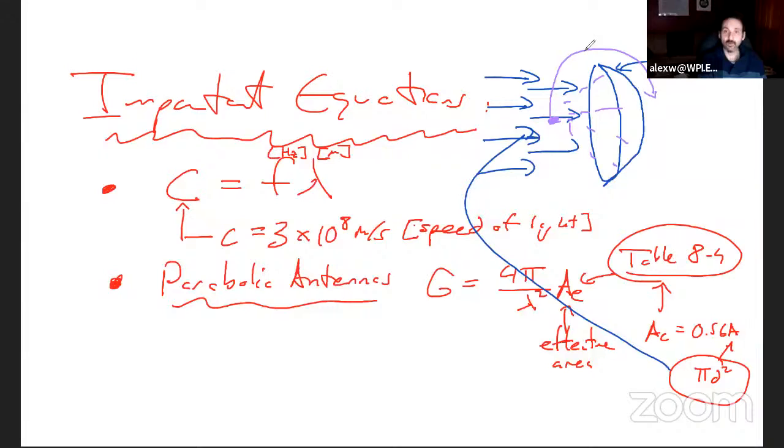The effective area is actually the entrance. Imagine this circle at the mouth, the top. If you were to put a piece of paper across that dish, the area of the paper that follows the silhouette of the edge of that dish is the effective area, right? So the D, the diameter, is the diameter across the top, the mouth, of that dish.